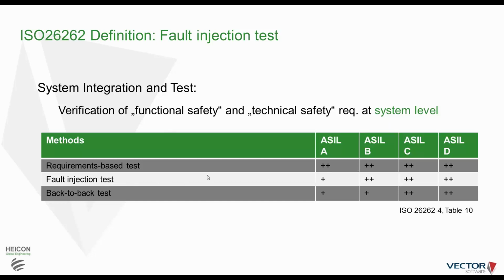But also here it's stated fault injection testing, and for ASIL A it's recommended, plus means highly recommended. ASIL B, C and D highly recommend also, in addition to the requirements-based test, the fault injection test. Not so much in focus of this presentation here is the back-to-back testing. I want to highlight these two topics, requirements and fault injection.